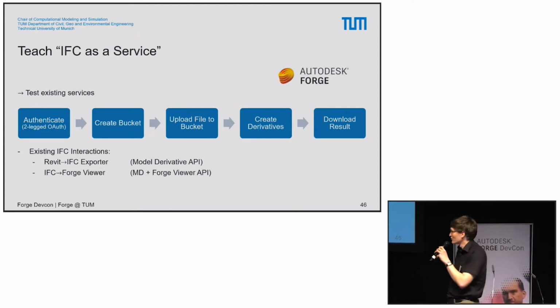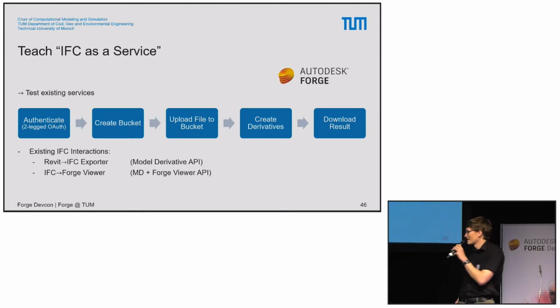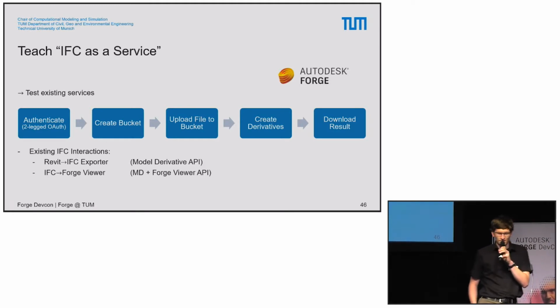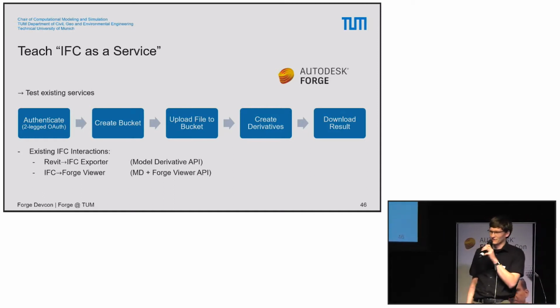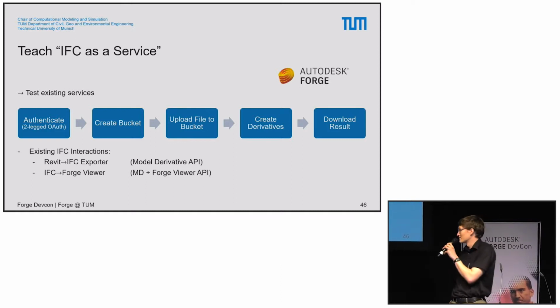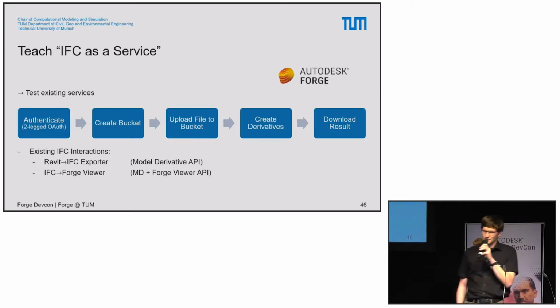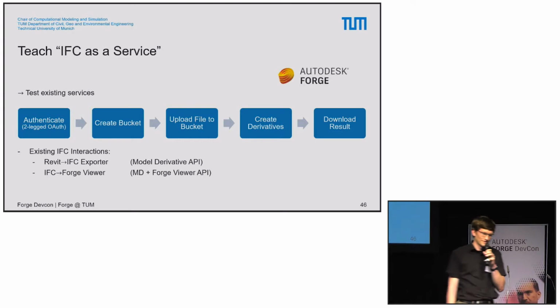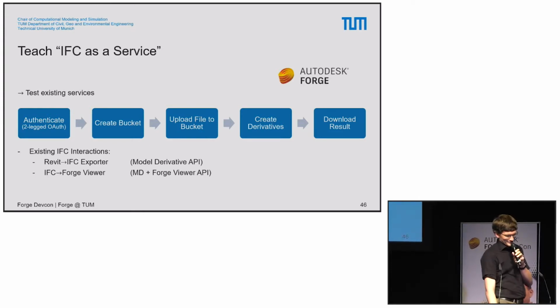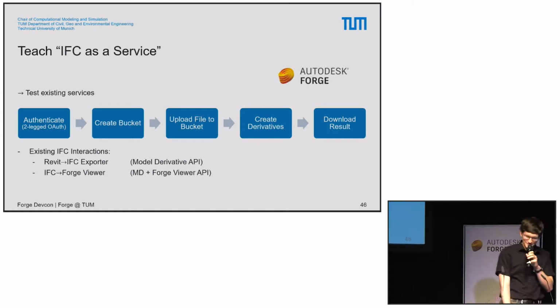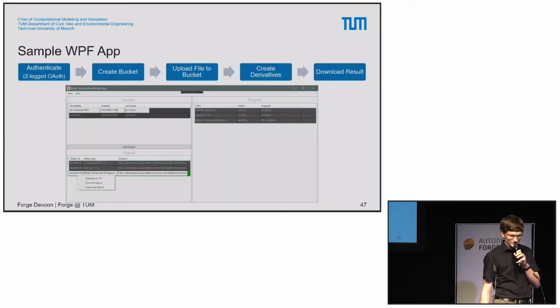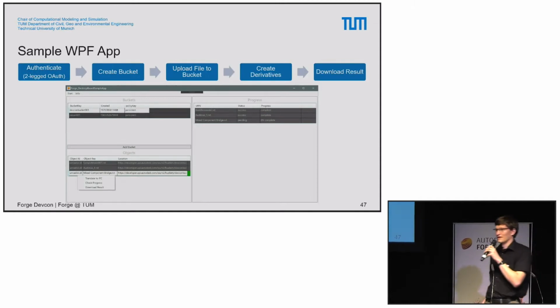What is the advantage of that workflow? Well, considering that I have 100 Revit models or something like that, and I want to export all of them towards IFC, I don't want to open every single model and press the export button. I just want to upload all these 100 models, start the translation job, and once it is finished, download the result. Well, there's no viewer in there. You can see the used APIs. It's not that fancy, that's the reason why there's no nice movie.